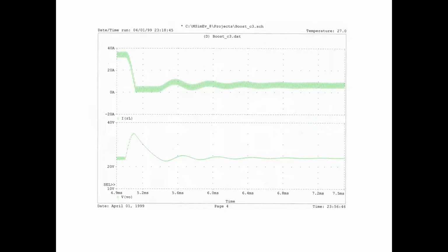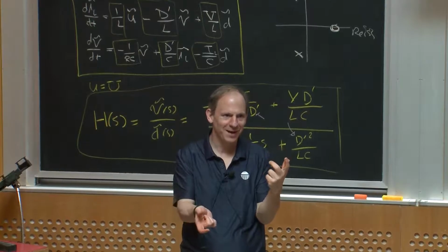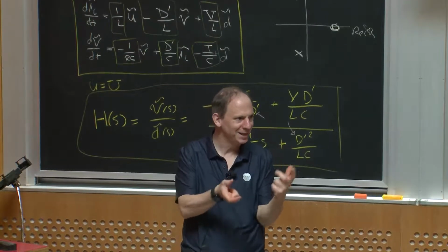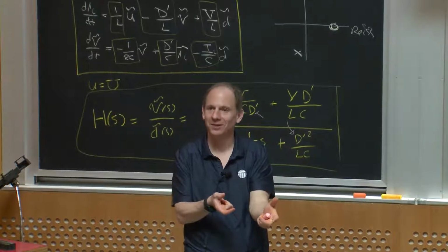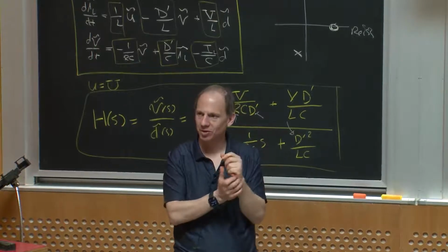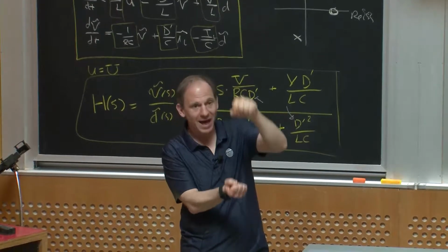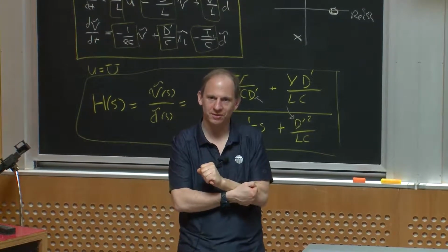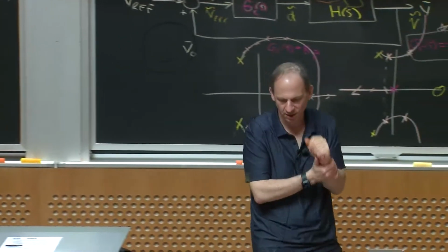okay? So when you're thinking in your design projects about how to size L and C and you want some cutoff, using a 1 Henry inductor and a picofarad load filter capacitor is probably a bad idea because you've got to eat the energy in that inductor in the load transient, right? So word to the wise, you got to size those very wisely and make sure you have enough energy storage in your capacitor that it's not going to be too unhappy to absorb the energy from the inductor in a transient. Okay? But more to the point, what else goes on here?